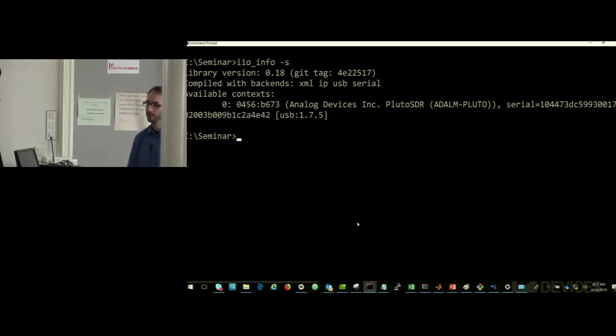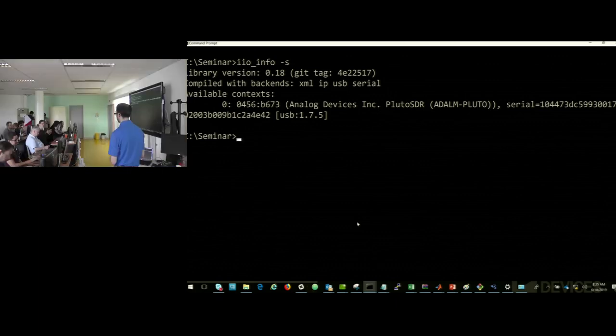You mentioned before that it's possible via USB On-The-Go. Yes, for example, a USB audio device being attached to the middle port when you power it from the other side. But that means that there are isochronous endpoints on the USB controller. Would it be possible to use isochronous for communication of the RF data between a Windows application or GNU Radio and the Pluto SDR? Because then you could probably have less latency, since you don't have all the caching and TCP/IP overhead. Yeah, if you use it as a serial device, not TCP/IP, that's what it will do. Okay, serial device. But it's still using bulk endpoints, not isochronous.